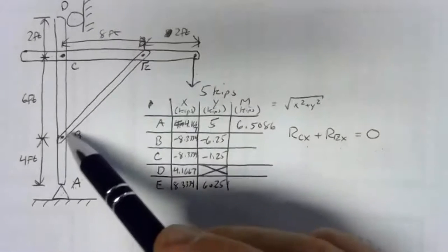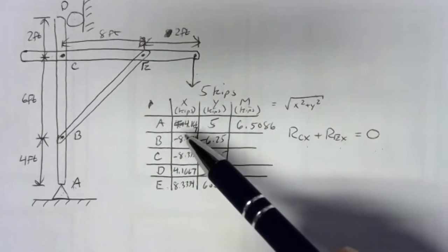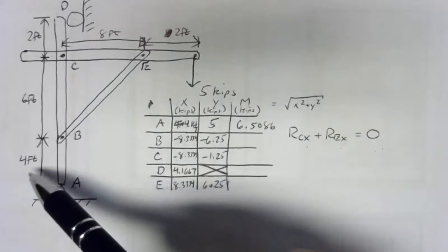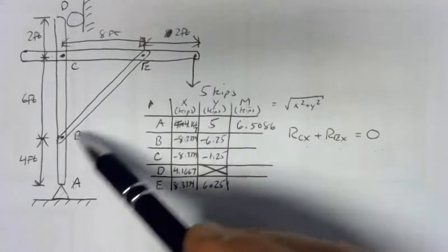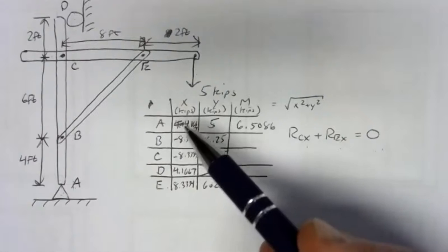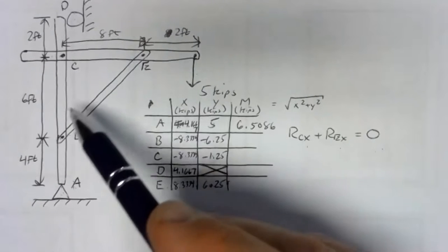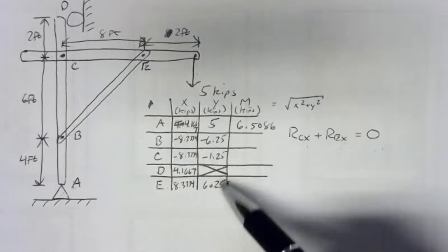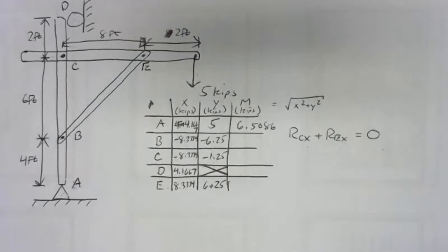member, it's a two-force member. So it's definitely got to have the same forces at both ends. That's what's needed to line up the force with the member. So two force members, whenever there are no other forces acting on the member except at the ends, you'll always get that behavior. You'll get the same exact values up to a sign.